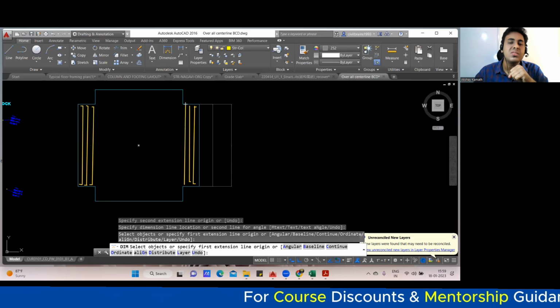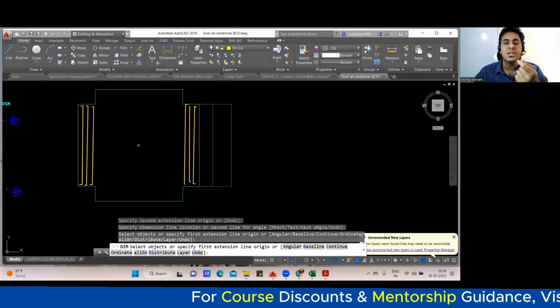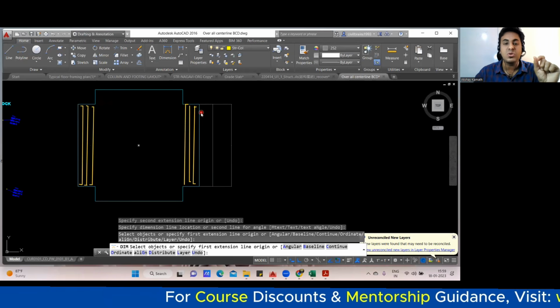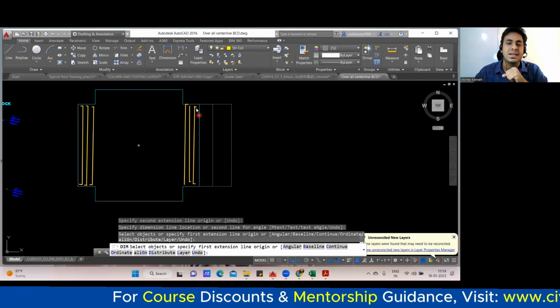Fine. So only this number of bars. I'm just showing three numbers. That may depend on this particular length. You divide by the spacing, you get the number of bars. Cutting length is very simple. Okay, this will be my cutting length.